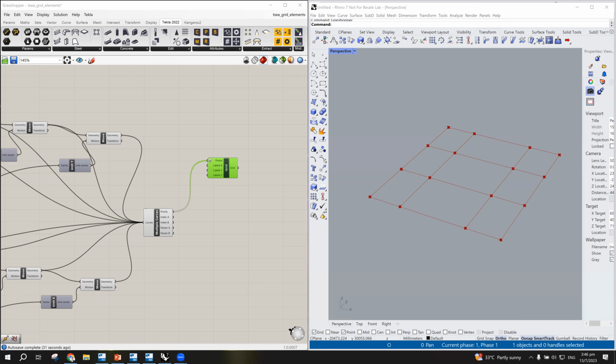Okay, so this time, I'm going to add the foundation or the pad footing first. Our aim is to create at least one pad footing. On top of the pad footing, there will be a steel column, and then on top of the steel, there will be a connection. There will be a beam connected to the column.